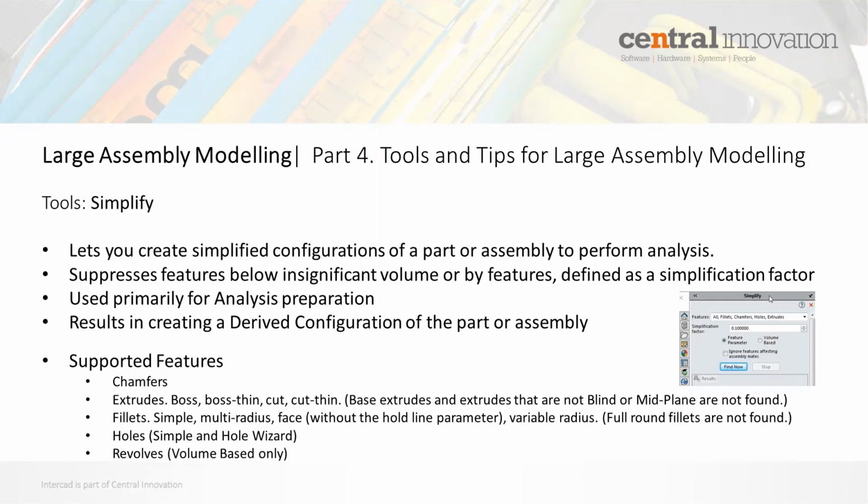This tool is really there to simplify configurations of a part for use in analysis, so finite element analysis, simulation. It basically allows you to suppress features below insignificant volume or by features, defined as a simplification factor, and it's used primarily for analysis preparation.